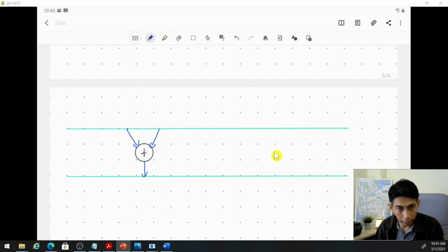But in scheduling and allocation, we need to allocate the resources to our design. In this case, we assign this to a register. In this example, I use a dot to represent a register, so no need to use a box, because it will make your drawing more complicated. This one we assign to R1 at the first cycle.